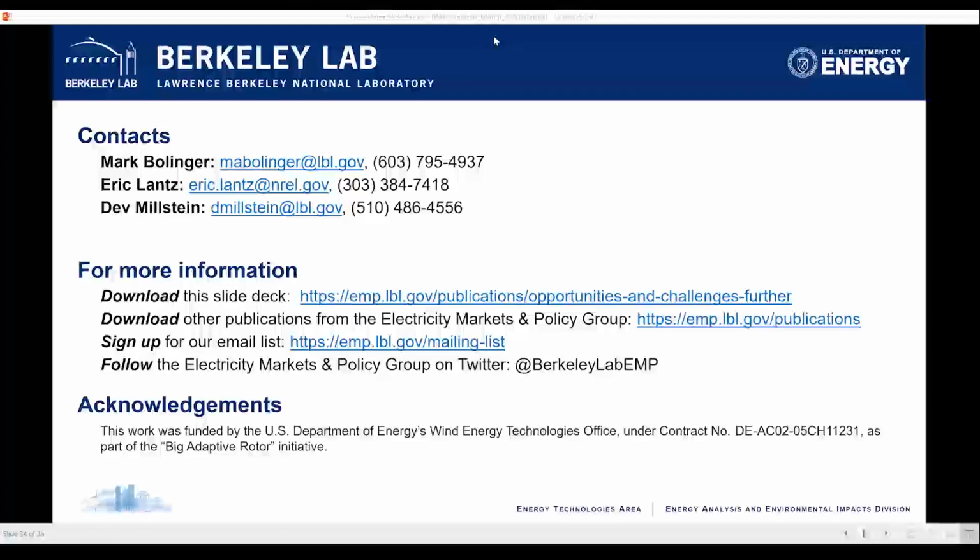For example, the latest round of offshore turbines are up in the 12 megawatt range compared to maybe 4 to 5 onshore. And so to get down to a low specific power level on a 12 megawatt turbine would just require a really large blade.